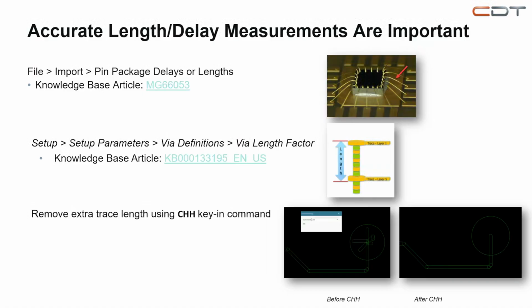We set it to 0 by default because otherwise we get a lot of questions from people confused about where the length comes from, because they measure the trace length on the layer and don't see where the extra length is coming from. But it's just between layers, so vertical. And that's something you do on the layout side, in the layout tool under the setup parameters.